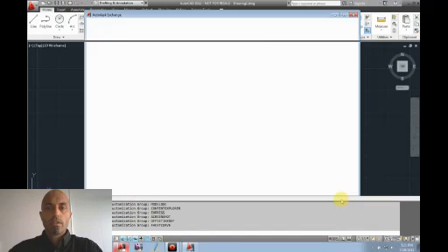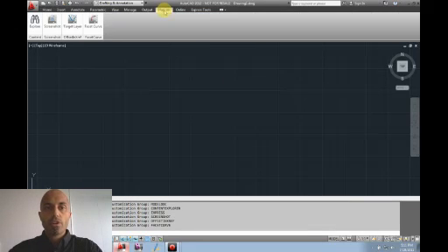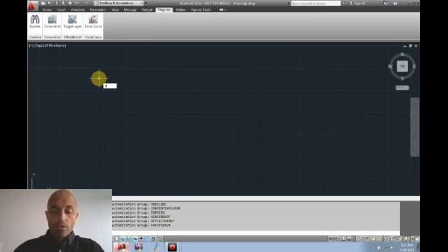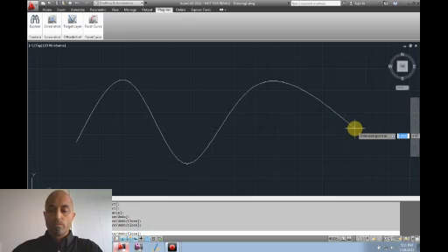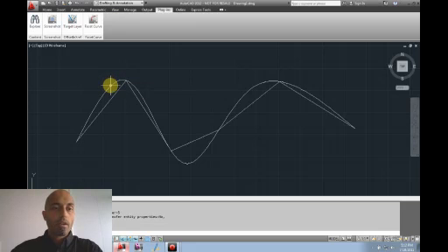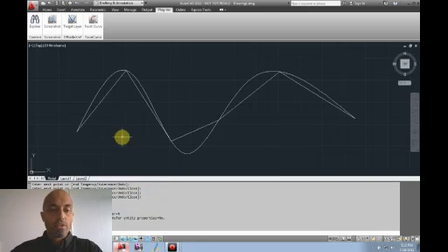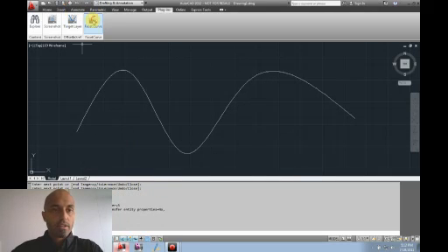So I'll close the Autodesk Exchange, go along to the plugins tab, and we'll find that this and a number of other applications that have been added are now loaded and available inside the ribbon. So what I can do here, for example, is create a spline, and we'll run this Facet Curve application on it. You can see it's got some default settings, which is not very granular. So one thing that we can do is undo that and then change some settings first.